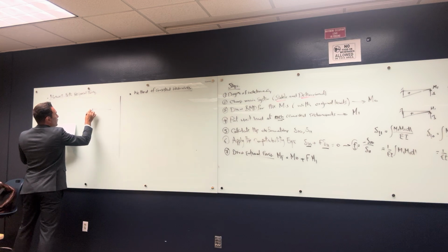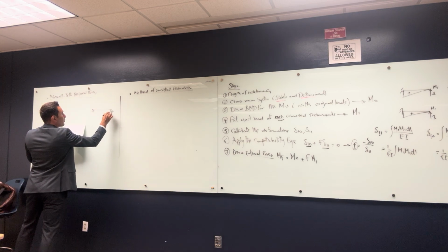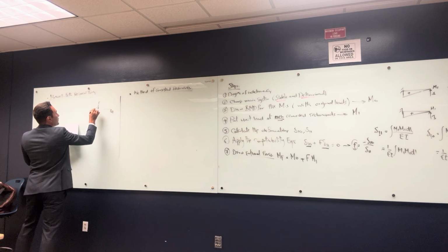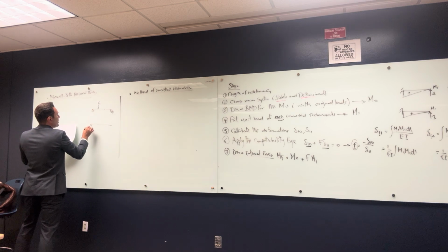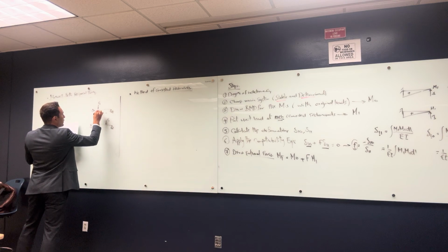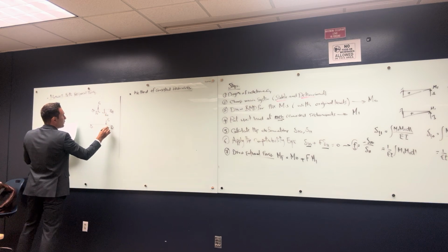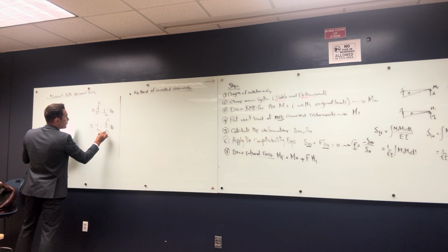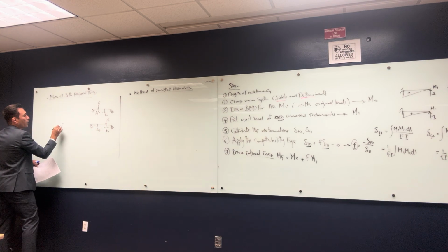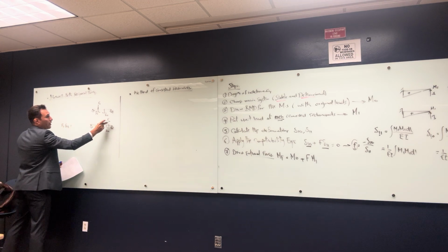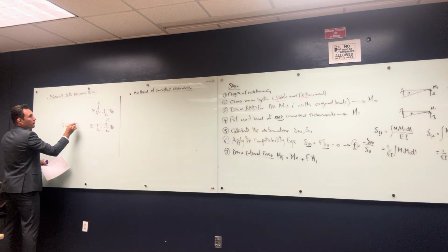This theory says that if you have a beam and you put a load F1 at point 1, and on the same beam at point 2 you put F2, this gives you a deformation. Here's the deformation, it's delta 1,1. This is delta 2,1. The other load gives you a deformation something like this. This is delta 1,2, and this is delta 2,2. F1 multiplied by the deformation from the second load, delta 1,2, is equal to F2 multiplied by this one, delta 2,1.